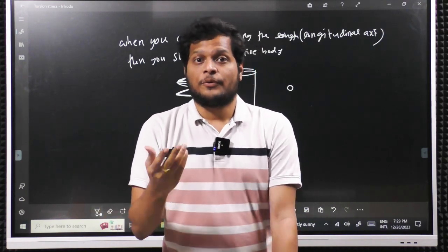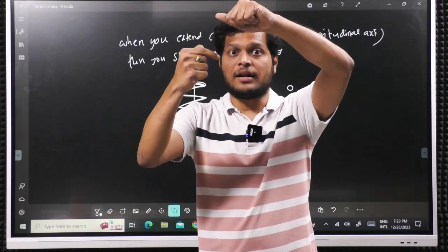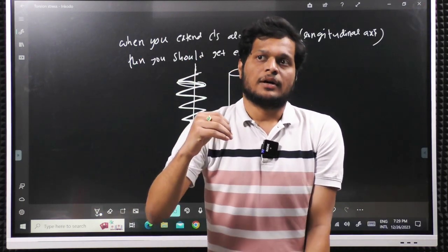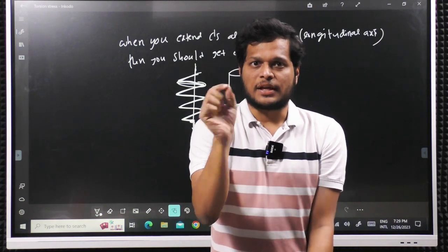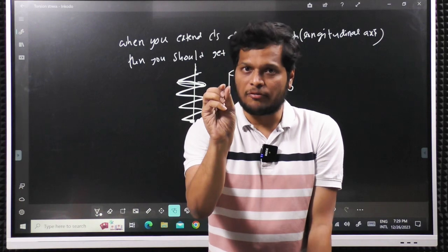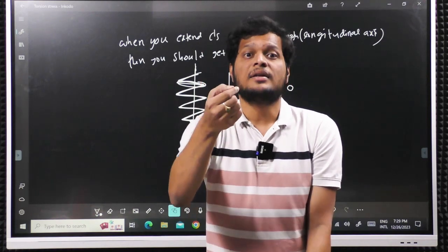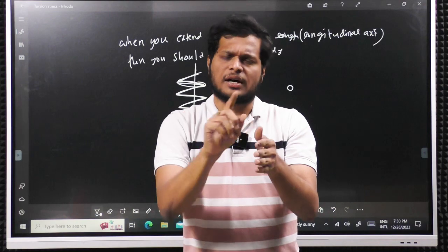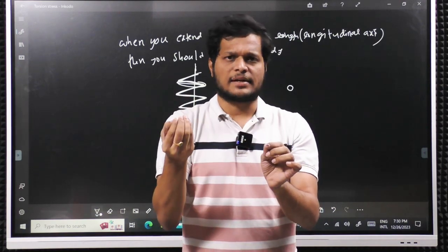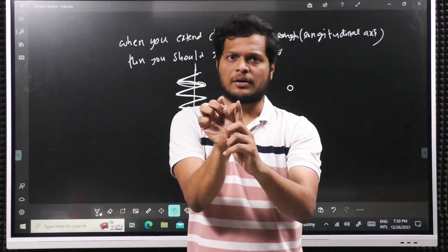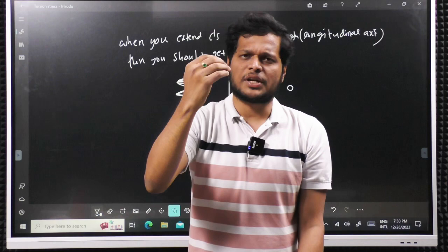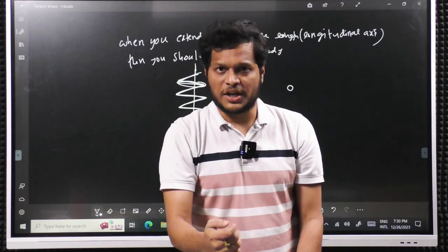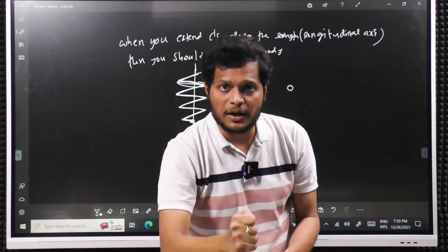Okay, so when a closely coiled spring is stretched, every layer of the spring gets twisted to a different amount. Okay, so not different amount because for load into eccentricity, if you observe, it looks like same. The amount of torsion you apply is same, the amount of rotation is different because this rotation accumulates to next level. The amount of torsion you apply is same because load into eccentricity. So everything is at a distance of small r. Everything is at a distance of r, but the amount of rotation varies from one section to other because this rotation will accumulate next level and combined rotation whatever you have will apply at the bottom and it goes down.